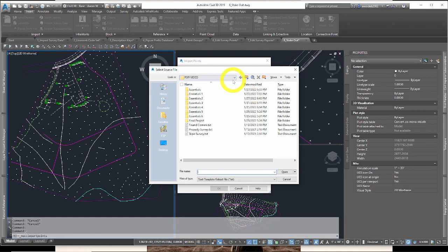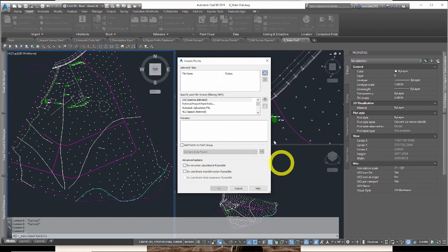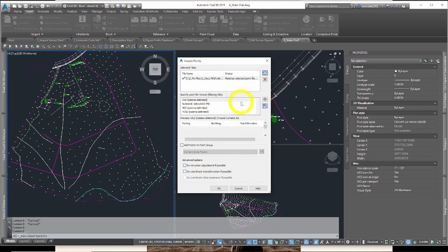and we're going to look for the found corners, which should be in your chapter 3, all your downloads. Many files, and it's a txt file. We'll hit open. Remember not to have the file open or it'll error out, so close out. Don't be in the file while you try to do this. And we'll do P-N-E-Z-D, comma delimited, which we're getting used to.